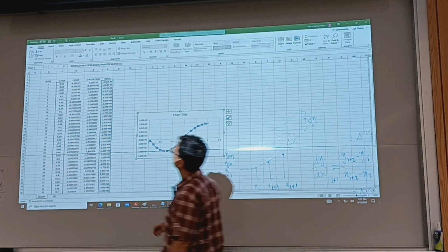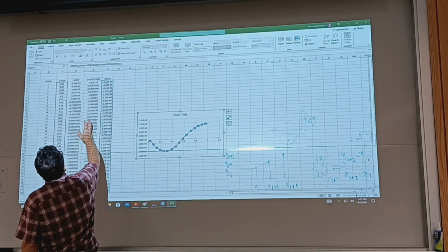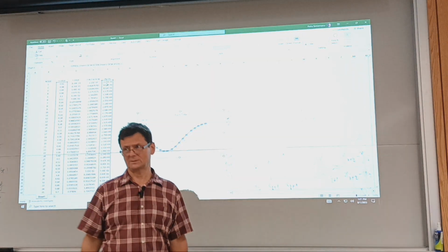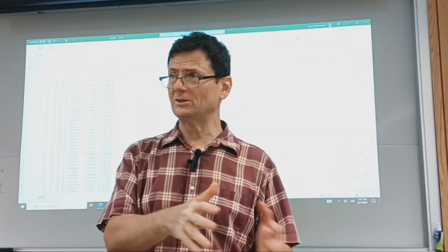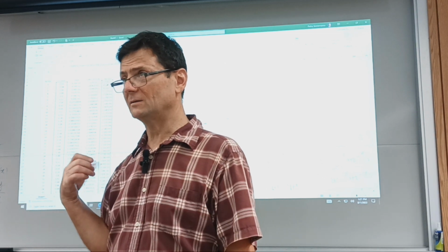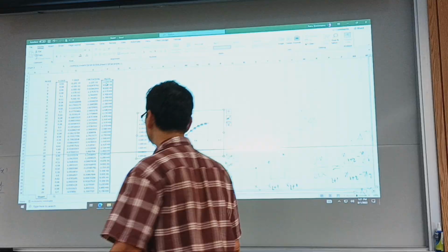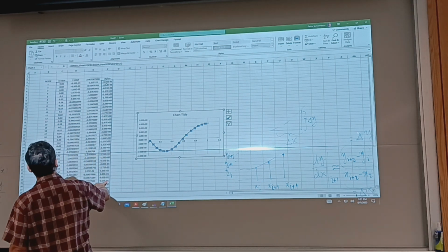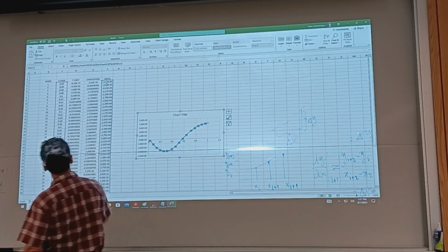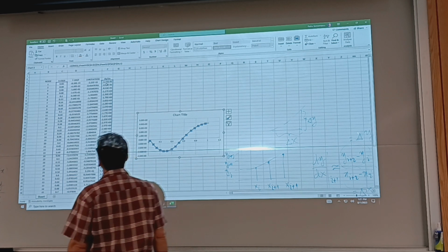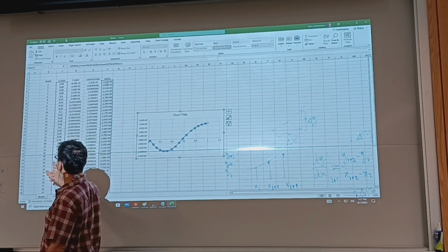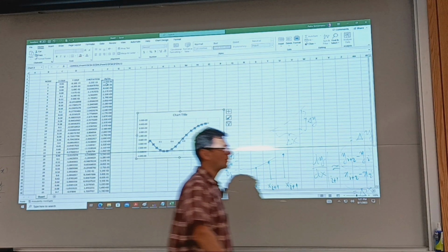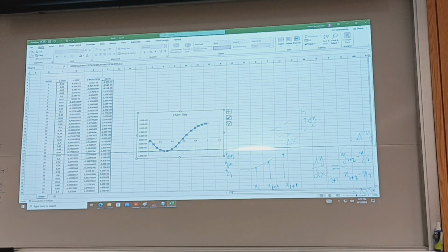So what I thought is missing, but what he calls z-rotation is the actual deflection. He does not, in the program, does not generate the graph, but it is available. You can get it exported. So whether you wanted to do the way I just explained, or just use the z-rotation, that'll be the slope. However, this appears to be an issue when receiving from his program the x values, due to the round off, it's cutting to no decimal. Okay, so that was one.